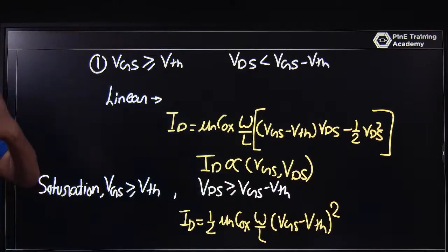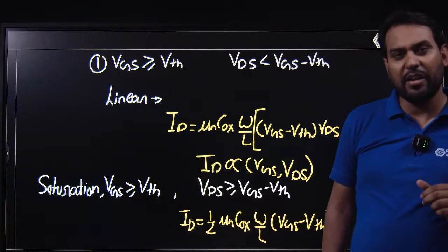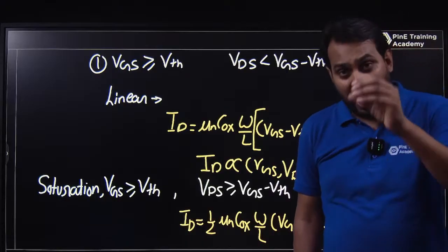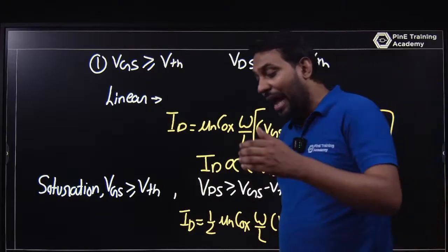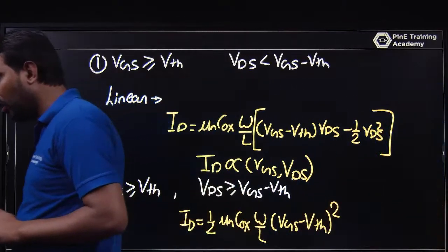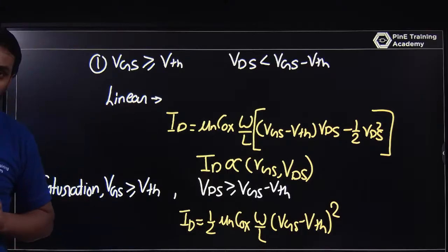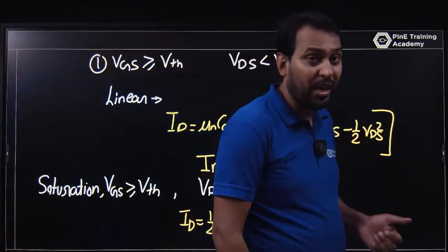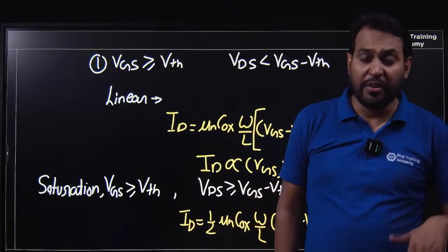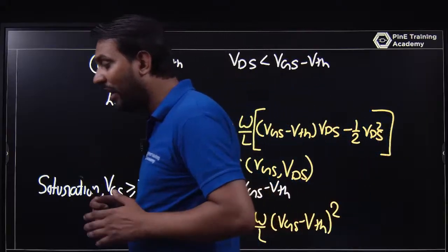Okay, so you go for FinFET. In a FinFET, you can work at a lower node, and the sub-threshold conduction has an effect, but not as much as compared to MOSFET. But if you reduce the length, of course you will find different parameters, that is second order effects. You will find velocity saturation, GIDL, gate induced drain leakage, and DIBL, drain induced barrier lowering.